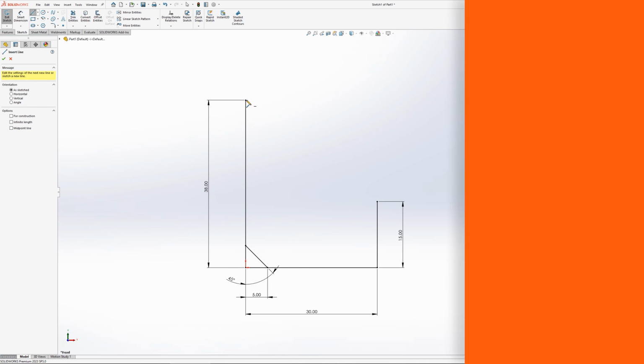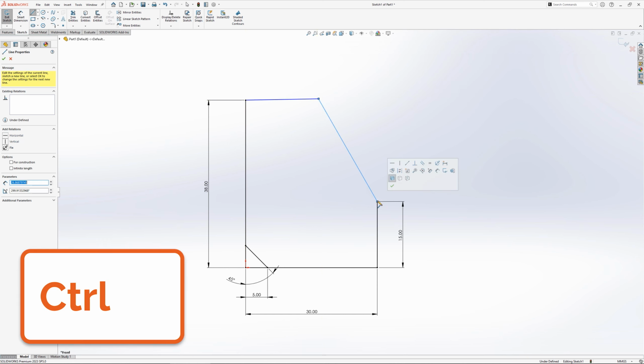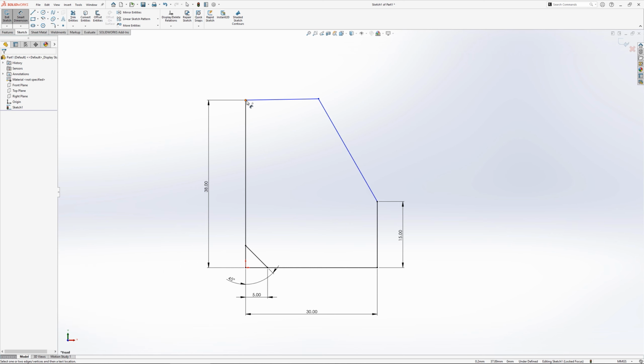By default, SolidWorks sketch entities snap into position and relations are added automatically. While sketching, if relations being automatically added need to be temporarily disabled, simply hold down the Control key. This is great for when a number of potential snap points exist within a tight area.